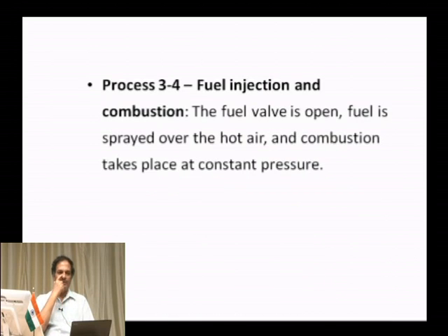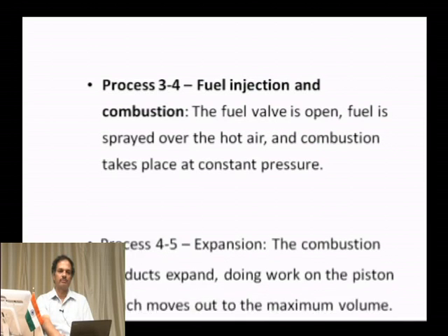Then process 3-4 is the fuel injection and combustion. So, at the end of the compression stroke, the fuel is injected through an injector or it is sprayed over the hot air and combustion takes place. So, that is process 3-4. It takes place at constant pressure.